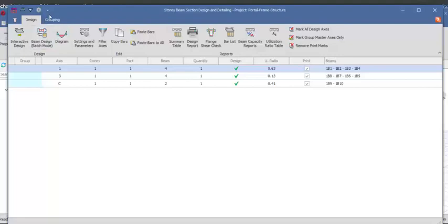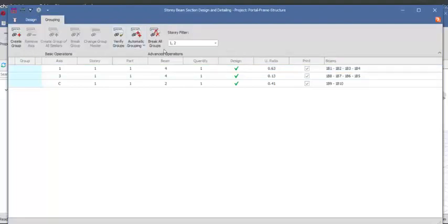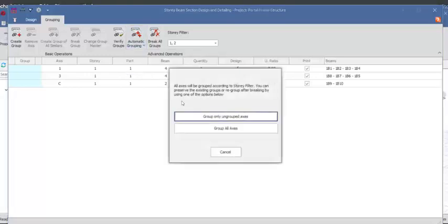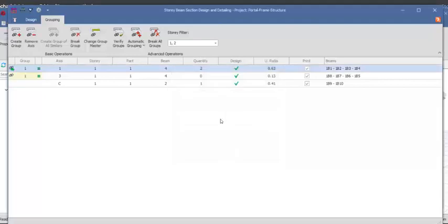Well, to group the beams, come to the group provisions and then come to these provisions where you have automatic grouping. Click on this provision. So group beam axis vertical, group beam axis within floor. Click on that provision and then group only on group axis. Click right there. So you can see now these two beams have been grouped successfully.